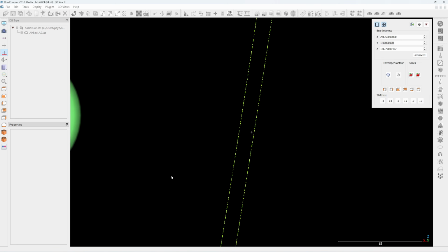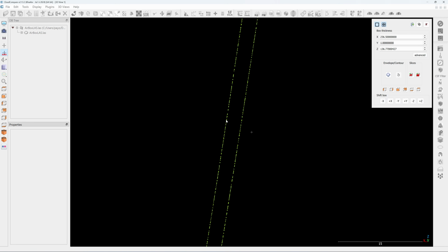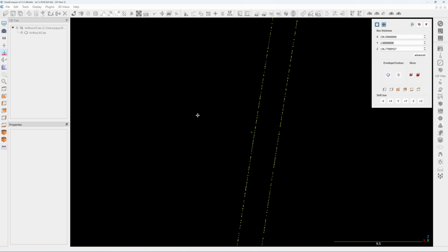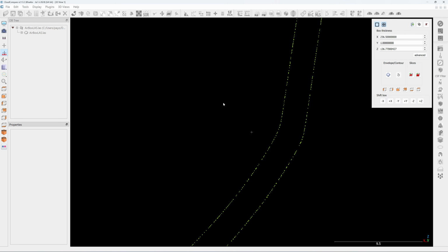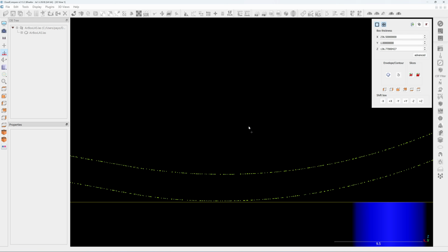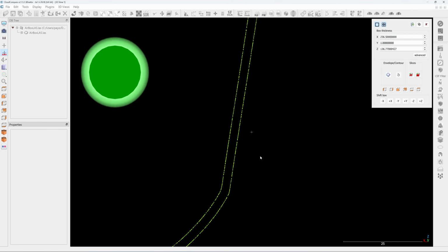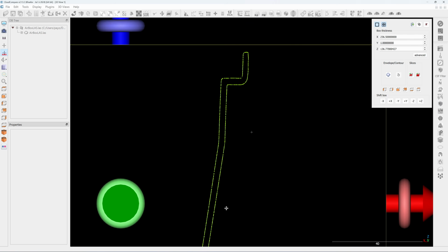Okay, see this thin line? This line is less than 20 microns. That's the precision of the 3D scanner. You can see this line. So the lines that I'm going to use for tracing are very thin and sharp. See, there is no noise, no visible noise anywhere. This indicates the quality of the scan, and it will make reverse engineering much easier if you have a sharp and clean scan.